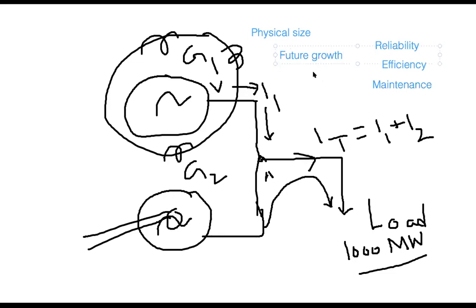What is the meaning of that? For example, you have two generators that are meeting a demand of 1000. Now as the days go, consumers' demand will increase. For example, now their demand is 1500 megawatt after installing these two generators. How will these two generators provide 1500 megawatt? They don't have such capacity. Therefore, if you have other generators connected in parallel, only then can they support that.